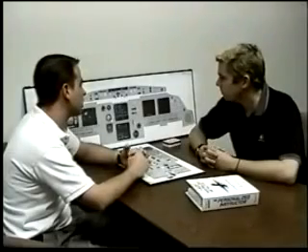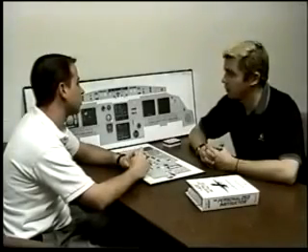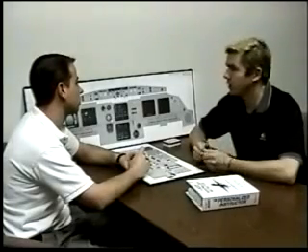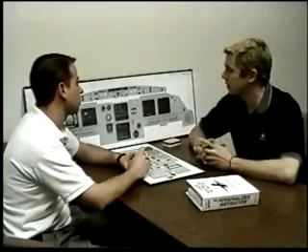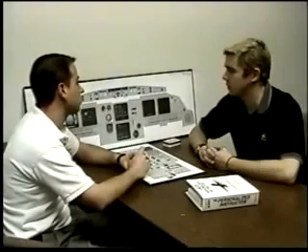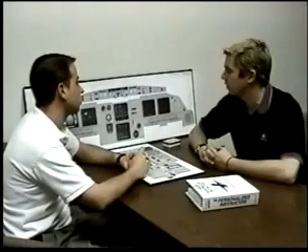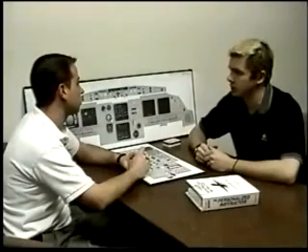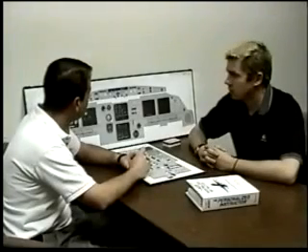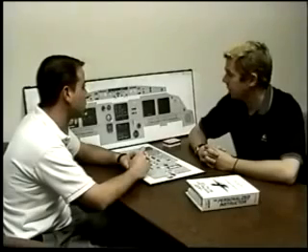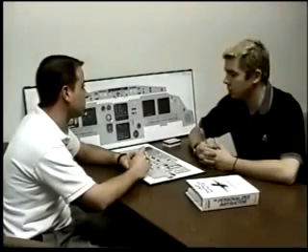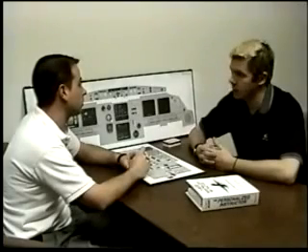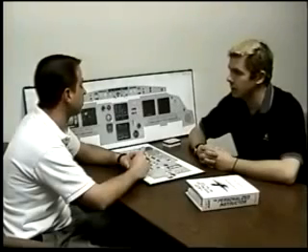Any speed restrictions with the landing gear? Yeah, there's three big ones in the limitation section. It's 220 knots and 0.54 for gear retraction. For gear extension it's 250 knots and 0.60. And then for gear extended, it's 280 knots, 0.67. While we're on gear, what are some tire pressure limitations? As far as tire pressure, we've got the nose wheel, which is always 180 psi. For the 320, the main landing gear is 210. For the 319, it's 187.